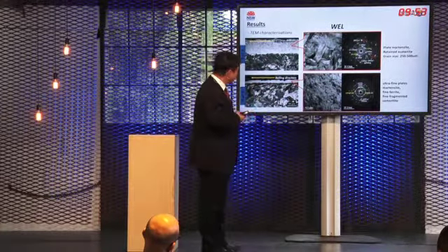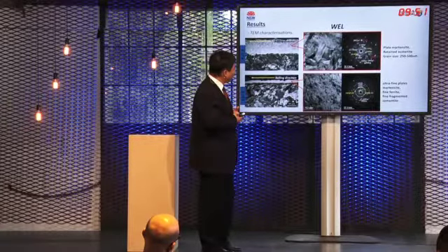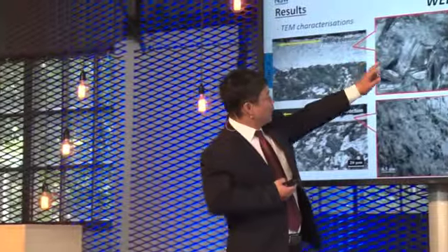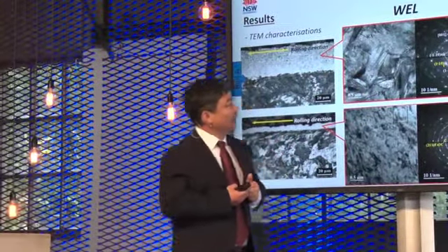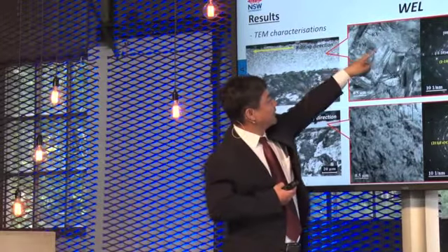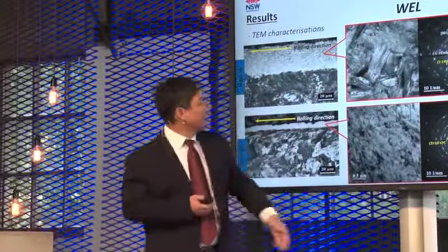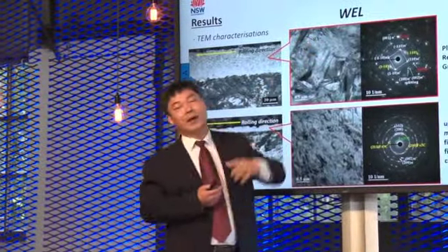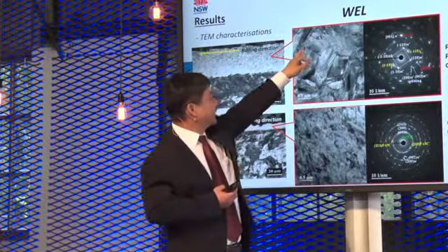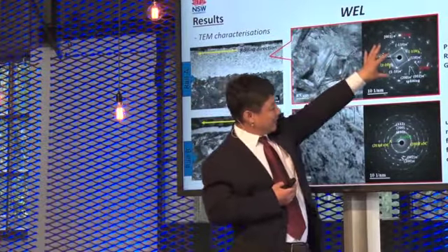This is the visual difference. Let's take a look in more detail. In the high braking region, the white etching layer consists of plate martensite, and also retained austenite. We confirm the martensite and austenite by the diffraction patterns.